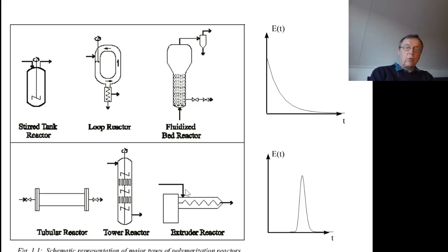So this is especially true for polycondensation reactions or for polyaddition reactions. So there we have to apply these tubular reactors, while for other reactions where the active sites are really short-living species, it doesn't make a big difference how long they stay inside a reactor. They produce their macromolecule anyway within a few seconds, and this short period of time is available no matter what the residence time distribution inside such a reactor is. And this is true for the free radical polymerization or for ionic polymerizations.